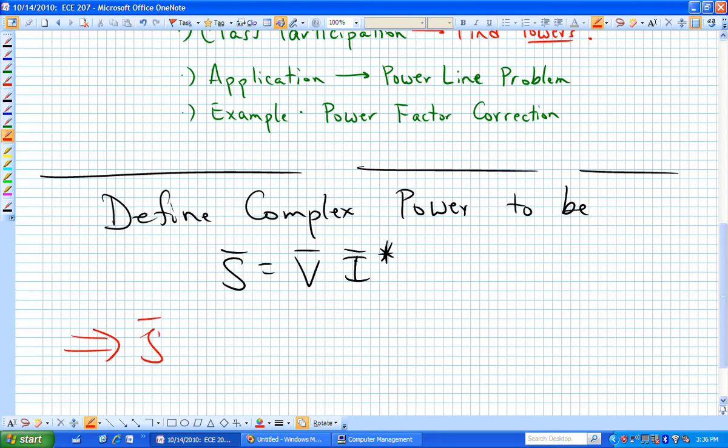If we look at that in phasor form, or more explicitly, we have this V_RMS, which is a number at some angle, theta sub v. We have our current magnitude written or determined to be in RMS units, meaning if it's a maximum current, you simply divide by the square root of 2 to obtain the RMS value.